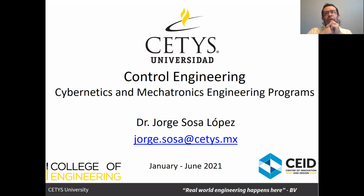Also, I know that depending on how the characteristic equation of the system is structured, I can also know the type of the system and how the steady state response is. And depending on how I plot or locate the poles in the S plane, I can represent different configurations of the system depending on different behaviors I want for a particular variation of a parameter. And that's called the root locus.